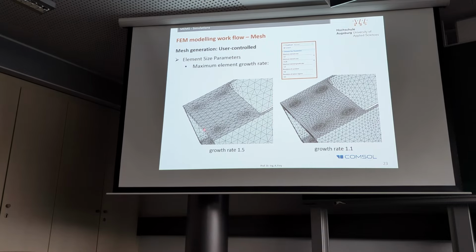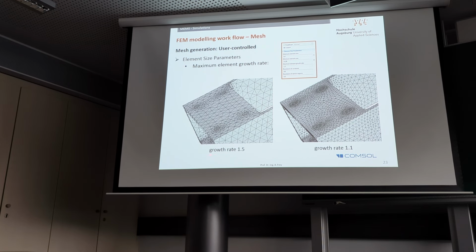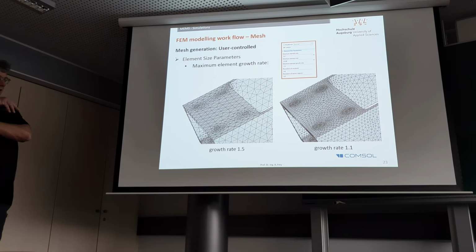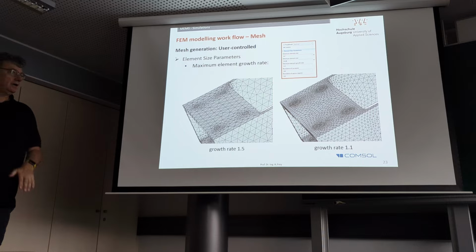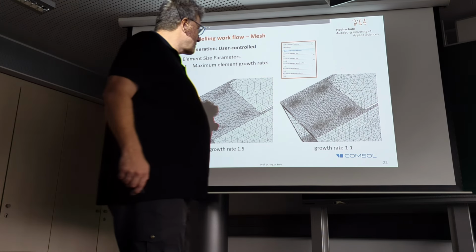And keeping a constant resolution of the curvature here, the difference is the growth rate. That is a higher growth rate, so it goes quicker to the more coarse element than here with the lower growth rate. So the fine resolution of the drilling holes extends into the body. That is just an illustration of how the growth rate works. And again here, you cannot make general recommendations like use always growth rate 1.4. Obviously, this is something you have to play around with and make a reasonable decision.